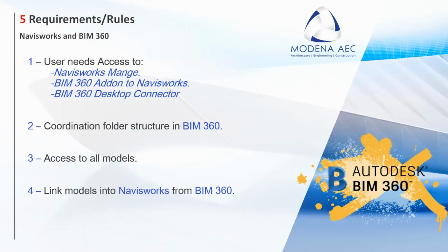So encourage your BIM managers on BIM 360 to give you this access so you can run your coordination from Navisworks. Rule number 4, link models into Navisworks from BIM 360. Yes, you can do that. As soon as you have a cloud model, whether it is Revit, AutoCAD, Inventor, whatever the case is, you can actually link those or append them into Navisworks utilizing the desktop connector, and then create the model in Navisworks and save back in BIM 360.